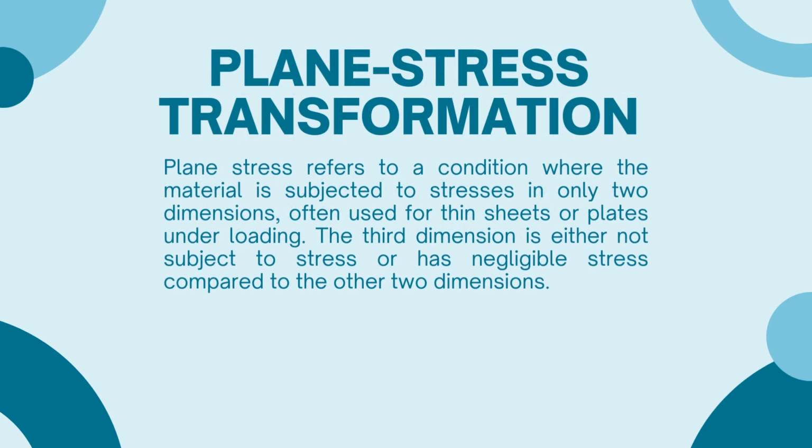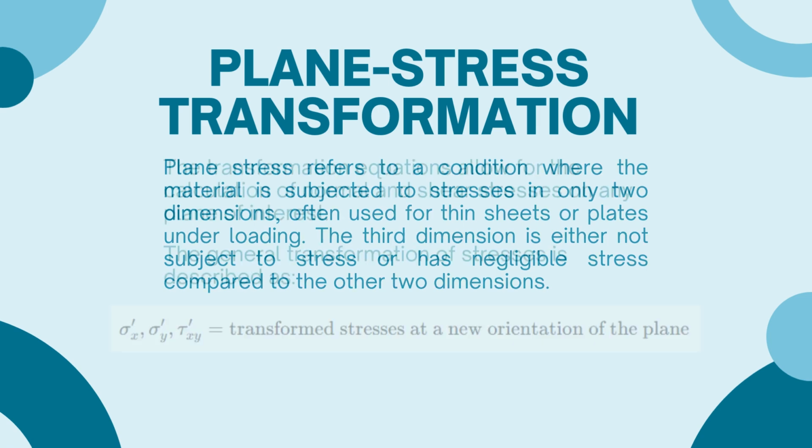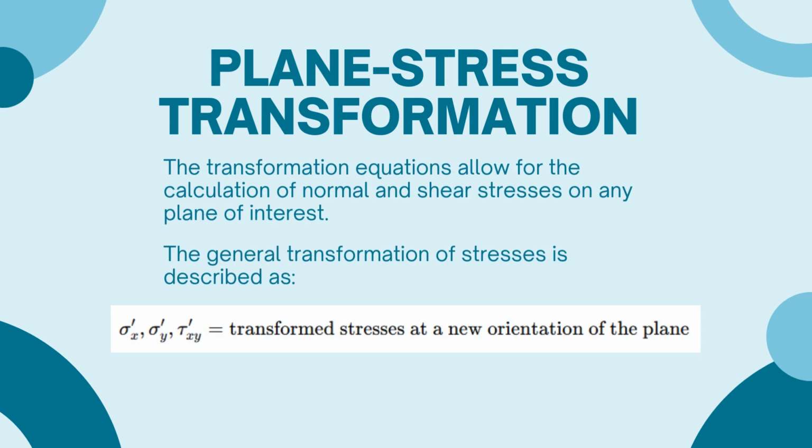Next, let's talk about plane stress transformation. Plane stress occurs when the material is subjected to stresses in only two dimensions. This is commonly used for thin sheets or plates under loading conditions. In this case, the third dimension is either not subjected to stress or has negligible stress compared to the other two dimensions. Understanding plane stress is essential for analyzing thin structures, ensuring their strength and integrity under different loads.